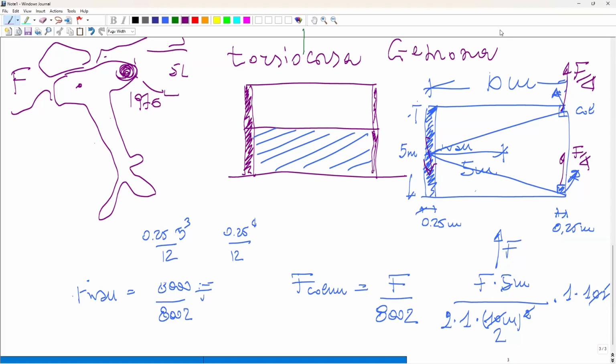It has remained as an example of bad assumption. Actually, that house really collapsed on itself. Because when the columns undergo a drift that they cannot resist, they lose support, and the house fell down.